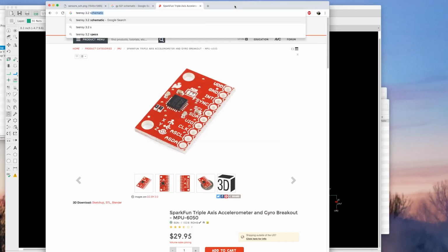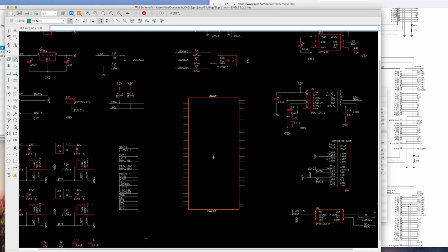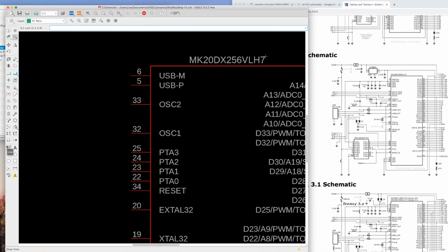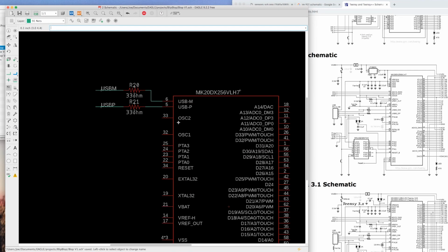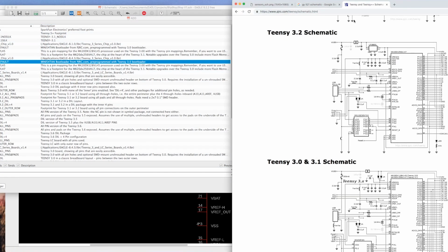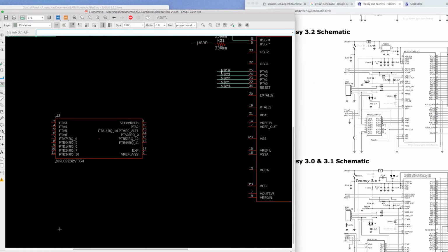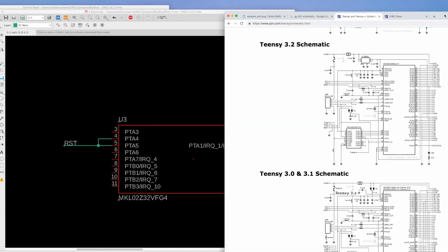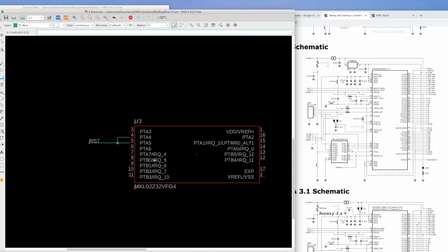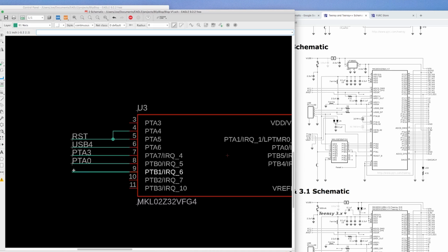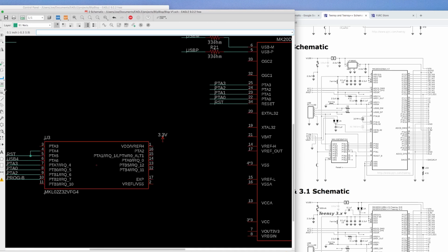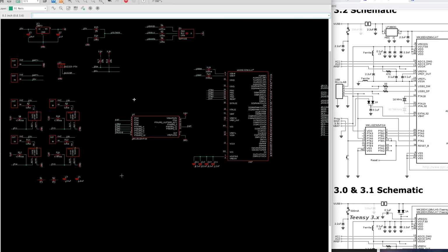So for Blop, the processor is going to be mounted directly on the main PCB instead of on the Teensy board for this computer. So we're going to need to replicate most of the circuitry that Paul from PJRC has really generously published on his website. The only consideration here is that we'll need to purchase a custom bootloader chip directly from PJRC, but that's a very small price to pay for the easy implementation of the Arduino environment on this awesome processor.